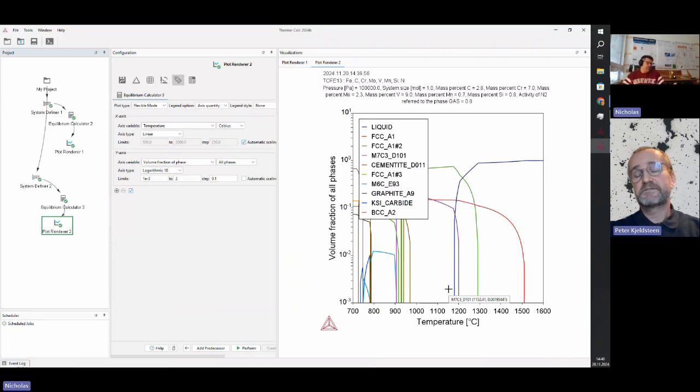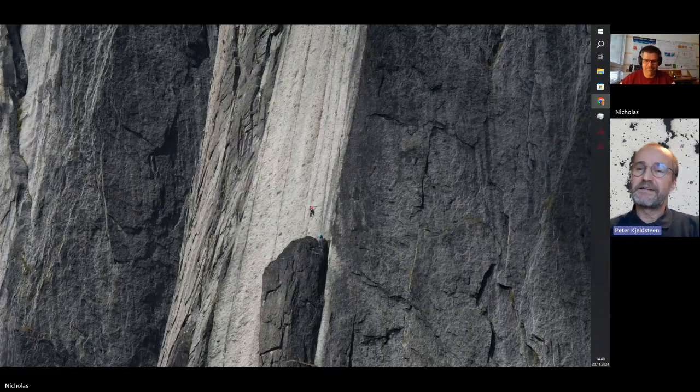Yeah. Okay. And I can disclose what we did because we found these nitrides and said then nitrogen might be the cause of our problem. So we installed an argon tank, and we changed our protection gas and our pressurizing gas to argon to avoid the nucleations, and it worked. So we never had problems again. Perfect. It's a nice example, because it's very clear from the calculation what the problem is, right? You immediately see that, right?